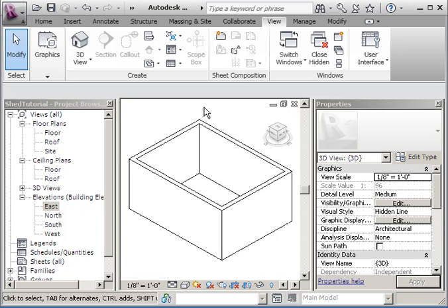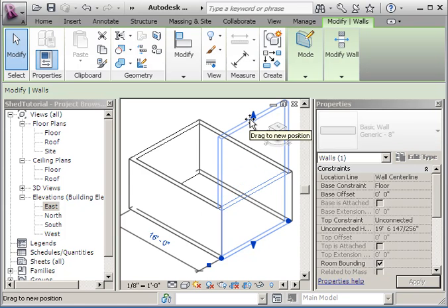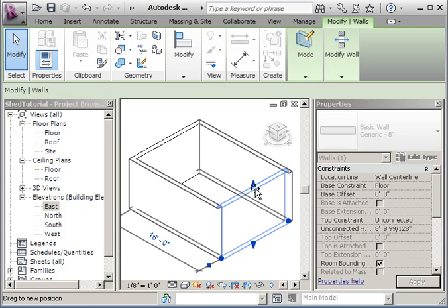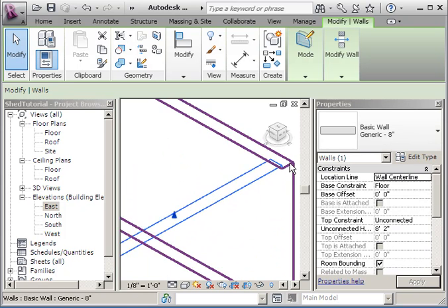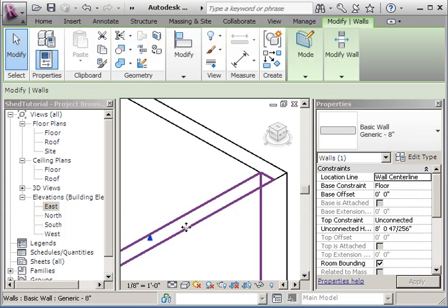The next step is all about changing the wall height. In order to change the wall height, you'll want to click on it and you'll get these arrows, and this lesson is showing you that what you can do is you can manipulate the height of the wall simply by dragging the blue arrow up and down and getting it in the correct position that you want. It's really hard to be accurate with that, though. I find it to be too hard to be able to get right on it unless you zoom way in on it. Then you can get a little bit more accuracy like that.